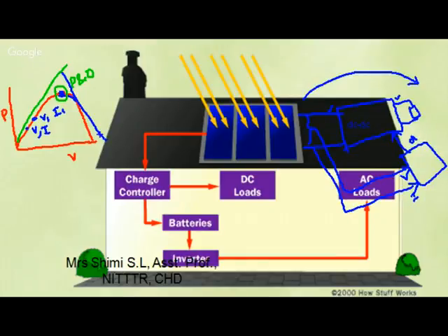उस maximum power point कहाँ है? The place where the impedance matches. वो impedance matching हम कैसे करवा रहे हैं? By using this buck converter, जो charge controller है उसकी duty cycle को हम change करके we can make the input impedance match the load impedance. I think it is little clear now, or should I explain it more?